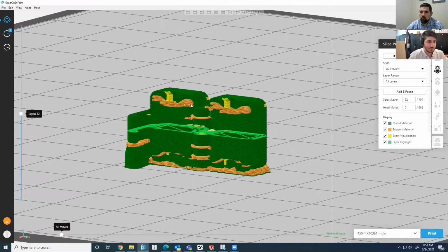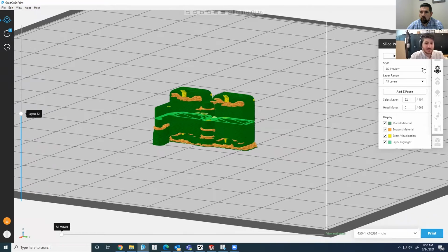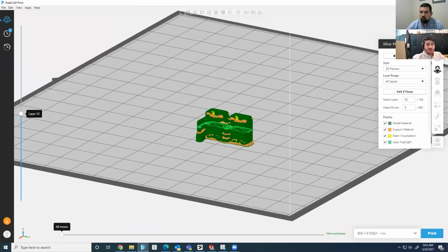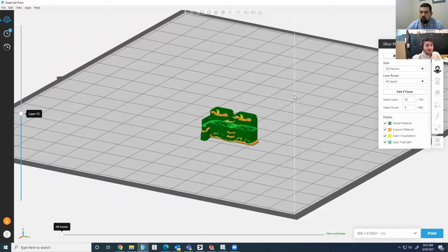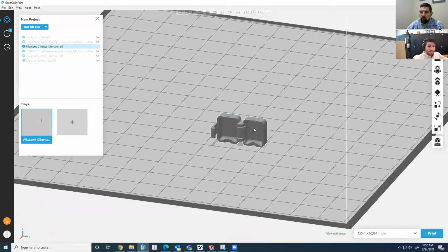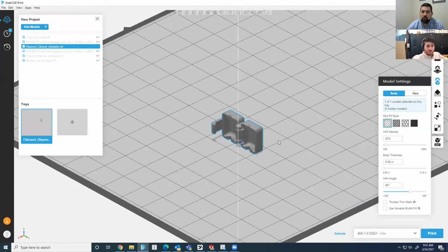So this material, you can just pull right out, and then you'll just have this face of support that you'll have to soak in the soak tank, which you'll have to do with nylon anyway, since it is, in nature, a very wet material. In order to produce a filament, it needs to be dehydrated, and it needs at least 8 hours after printing in order to rehydrate, get to its correct dimensions, which is all accounted for. The shrinkages are all accounted for in the slicing software, so you don't have to worry about sizing correctly. But as I was saying, this nylon material, as well as our nylon 6 and our nylon 12, all need to rehydrate after printing in order to have the flex that nylon is known for.